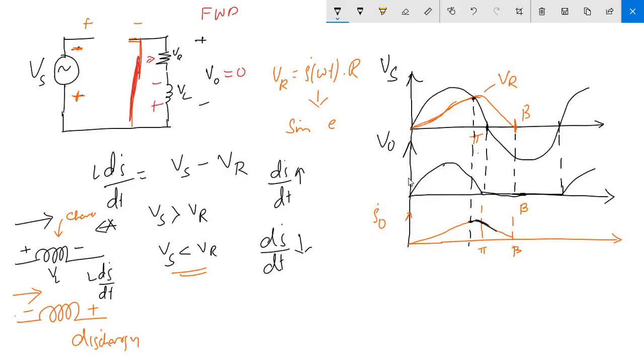Therefore, your main diode does not have to operate for the negative half cycle. That's the advantage of attaching a freewheeling diode across your load: the negative part is removed. The freewheeling diode operation matters only when you have an RL load.